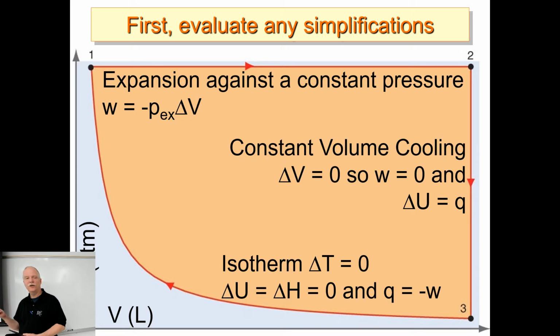Notice how to do all of these equations, we need things like the pressure, the volume, the temperatures. That's really the first step: looking at the situation, seeing if there are any isotherms and so on. The second step is pulling the equations and thinking about those. But the third step, before you do any calculations and try to use these, is to come up with what I call the state variables table.